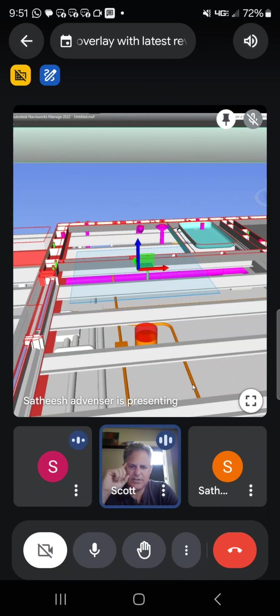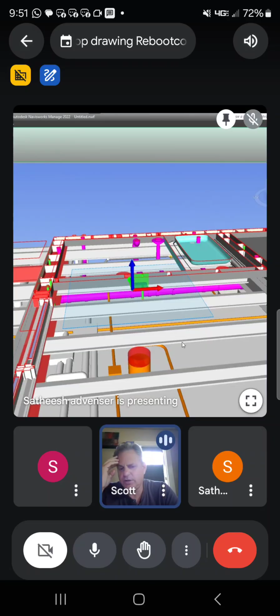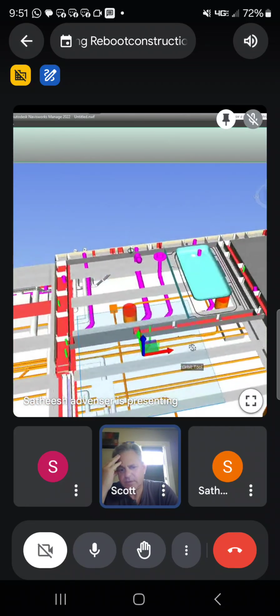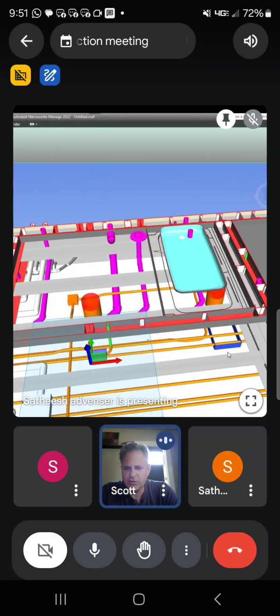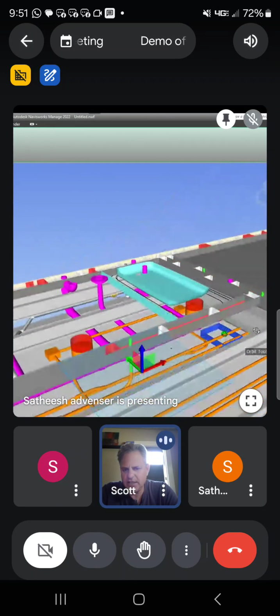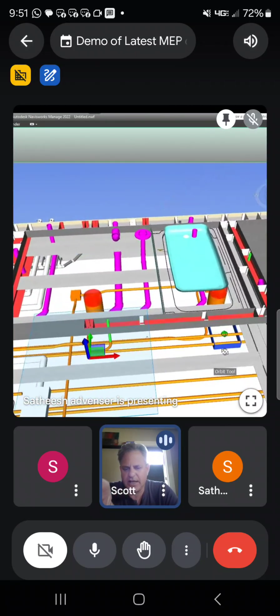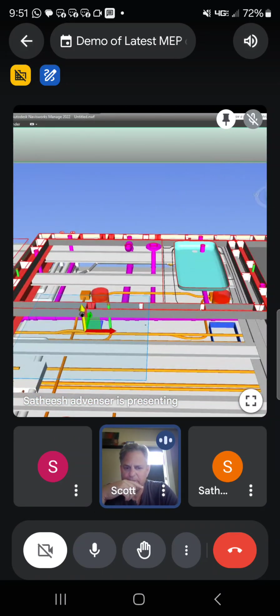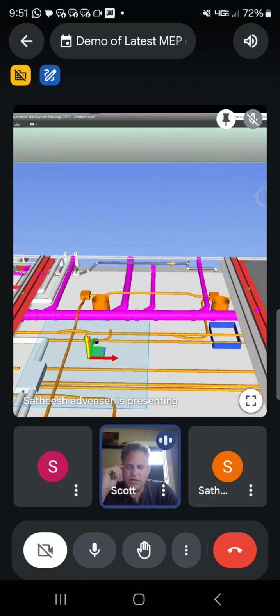Now, see that vent where the hood is? That needs to vent to the outside. And the way these floor joists are running, they're running the wrong way. That's what I'm wondering: if we can move it. We've got electrical going over that little box where he's at. There's a 4-inch vent that's going to come up and go out the side of the building right there, and the joists are running wrong for that.